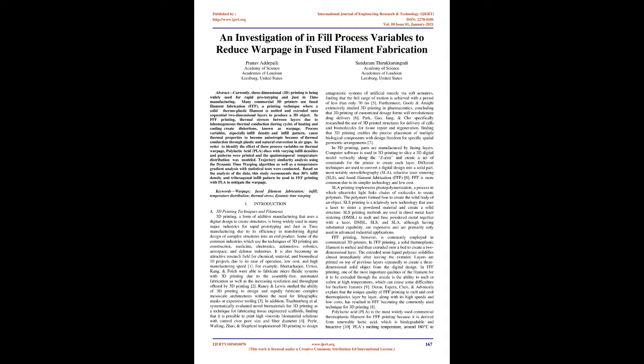known as warpage. Process variables, especially infill density and infill pattern, cause thermal properties to become anisotropic because of thermal conduction through plastic and natural convection in air gaps. In order to identify the effect of these process variables on thermal warpage, polylactic acid (PLA) discs with varying infill densities and patterns were printed and the spatiotemporal temperature distribution was modeled.